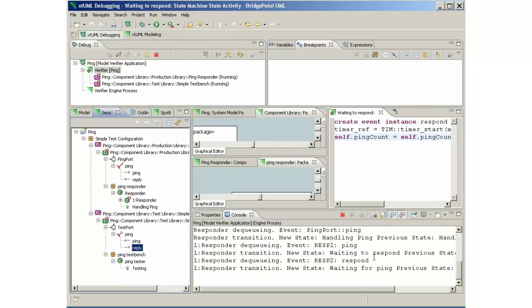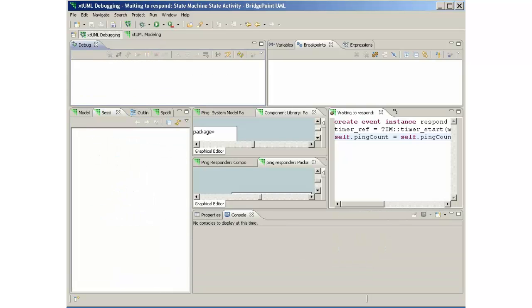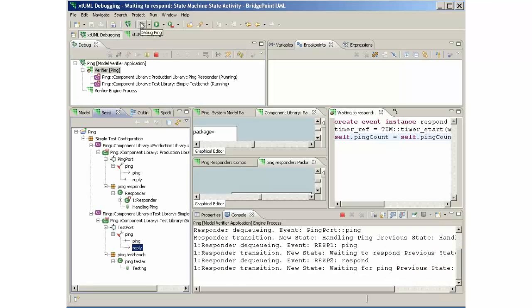When testing, launching a simulation is all that is required. The simulation output is all that's needed to determine if we got the expected behavior. If the behavior is not as expected, however, we need to stop the simulation and examine its state to find out why. There are several ways of doing this, manually and by setting breakpoints.